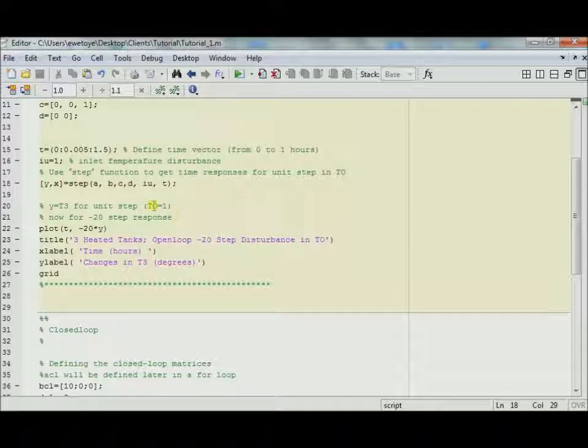that is a 1°F step response. Without the y and x in front of the function, it will produce a plot of a 1°F change in inlet temperature. But for the task at hand, we need that of a -20°F change in inlet temperature. Thus, we pass the y-axis values to y and other values to x.